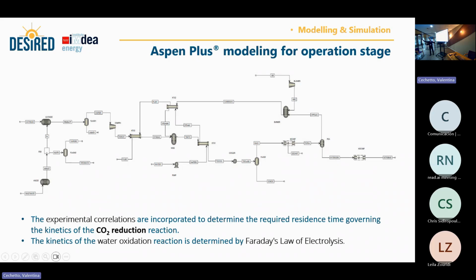To complete the process and have a single product, we apply the water gas shift reactor to convert the carbon monoxide to more hydrogen, to get hydrogen as the final product of our system. We did this integration in the process, and we also have purification using a PSA unit to purify hydrogen and then compressing hydrogen to the desired pressure.